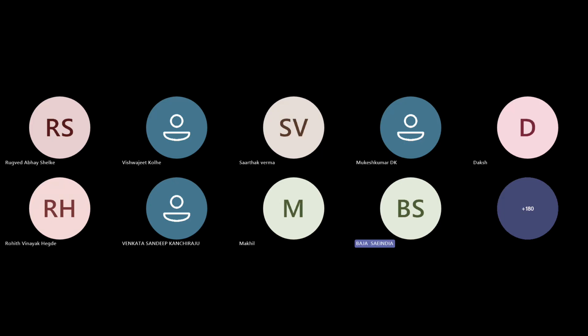Sir, what if my nodes are more than 50,000 for OBJ? How should I reduce that? While creating an OBJ file from any of the CAD models, you will have an option for the number of nodes. You need to reduce the count of triangles or nodes, whichever option you have in your CAD model. By that, you will be able to reduce the node numbers.